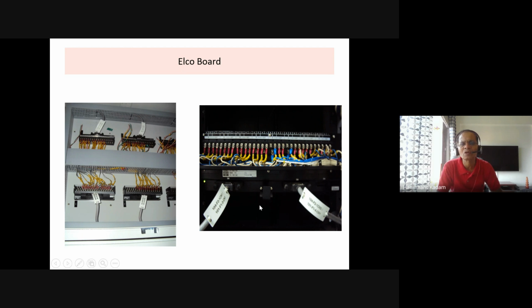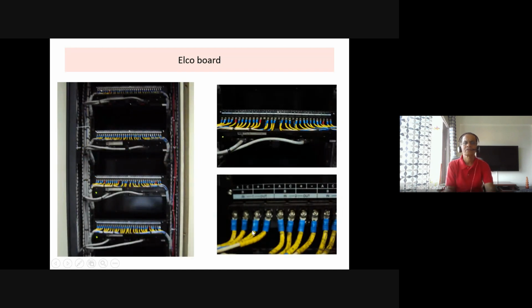This way, the Elco board is there, and as I told you, in the Elco, for example, you can see here two wires going out from here, which means these are redundant wires. So this is signal duplication. The signal is duplicated like this. So this is the Elco board electronics. Actually, Elco is the name of this electronics conversion unit by Yokogawa. Nothing else.